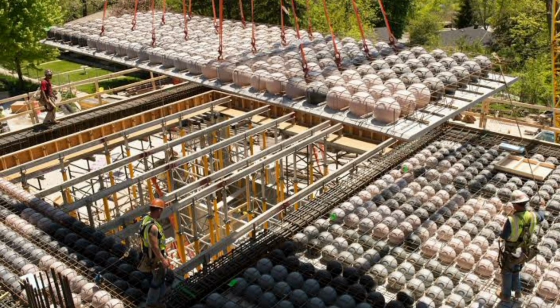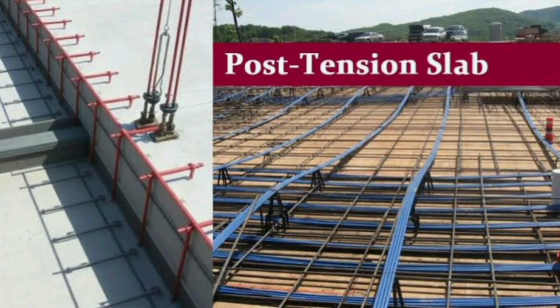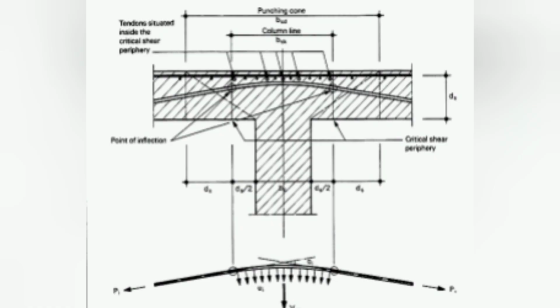Finally, we have to discuss the powerhouse of long-span construction, the post-tension slab. Post-tensioning involves placing high-strength steel tendons in plastic ducts within the slab before pouring concrete. After the concrete is cured, these tendons are tensioned using hydraulic jacks and anchored against the concrete, putting the entire slab into a state of compression. This compression counteracts the tensile stresses caused by loading, which effectively makes the concrete stronger and crack-free.